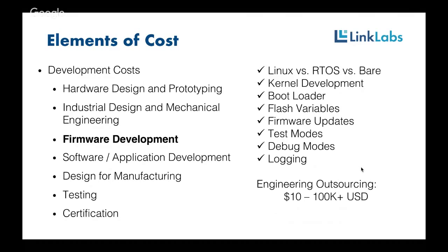Firmware updates, the ability to update devices over the air, so to speak, or even over the wire, is very complex because you're handling flash memory down at the register level and just keeping track of all of those, and encrypted binaries, very complex. Test modes that the devices will go into when they're being fabricated, or compliance test modes, like when you're doing FCC testing to generate tones and sweeps and other things to make testing easier, all go into firmware development.